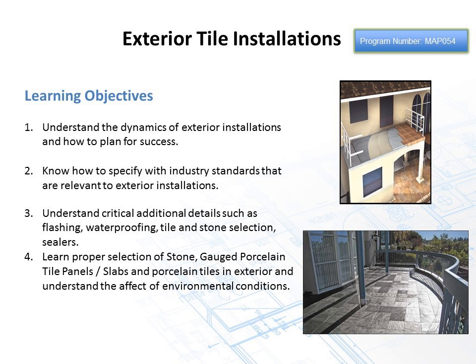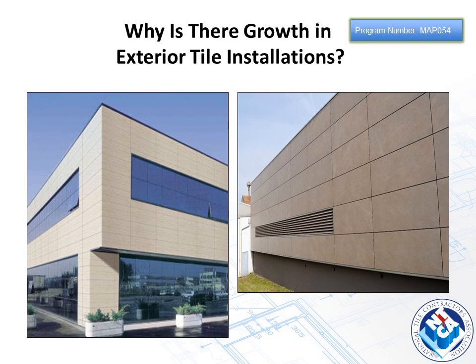How to specify with industry standards that are relevant to exterior installations. Understand the critical details such as flashing, waterproofing, tile and stone selection, sealers, mortars, grouts, etc. And learn the proper selection of stone, gauge porcelain tile, or porcelain tiles on an exterior and how they're affected by the environmental conditions.